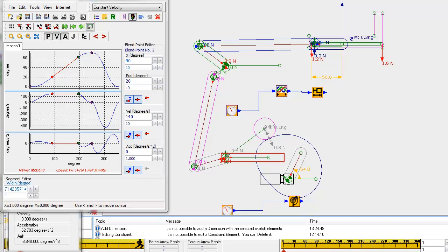So we could change just about anything to improve this theoretically, but I'm not talking about motion design, so let's just say we are stuck with the motion design. We need our camshaft underneath to keep lubrication and dirt away from the product, but let's suppose that we can move our centers a bit and change the link lengths.